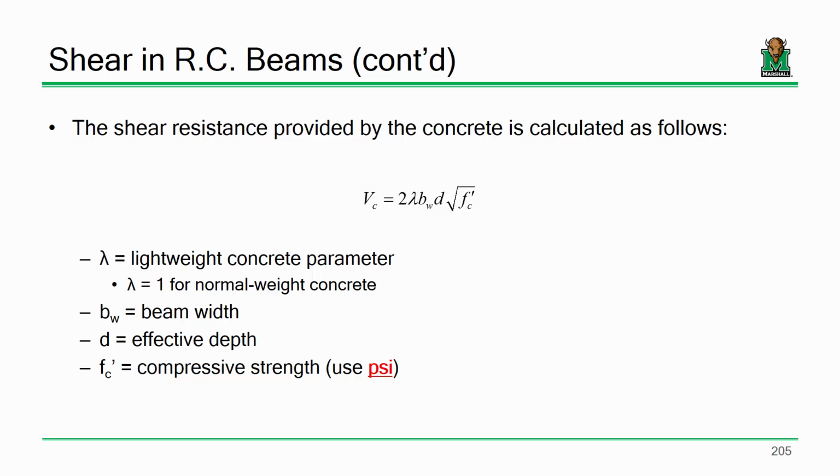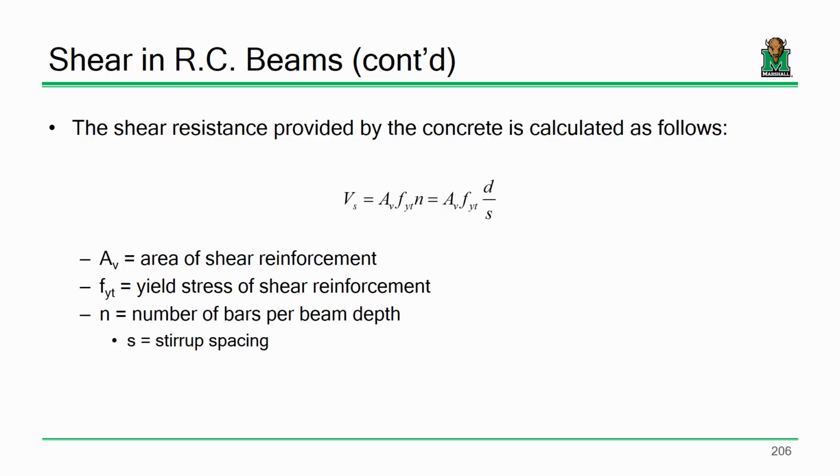Tell you what, do the rupture strength. Do 7.5 times the square root of f'c. Put in 4 and put in 4,000. Guarantee you get a different number. Because I'm right. All right. Now, is everybody okay with that?